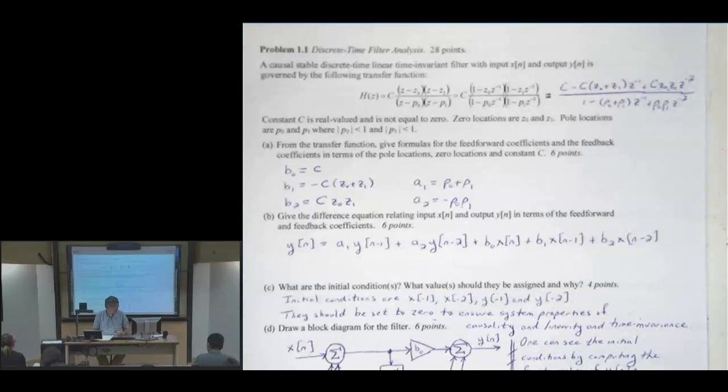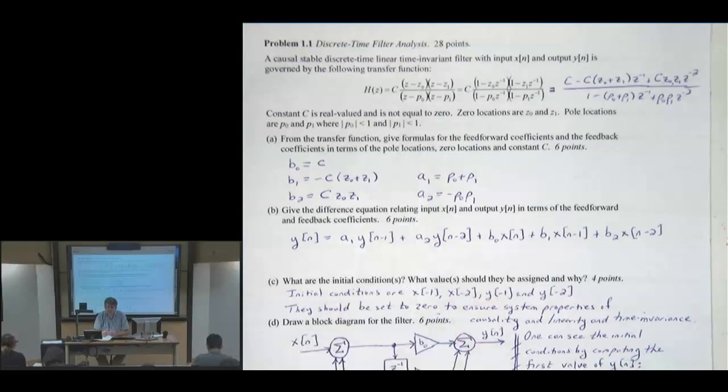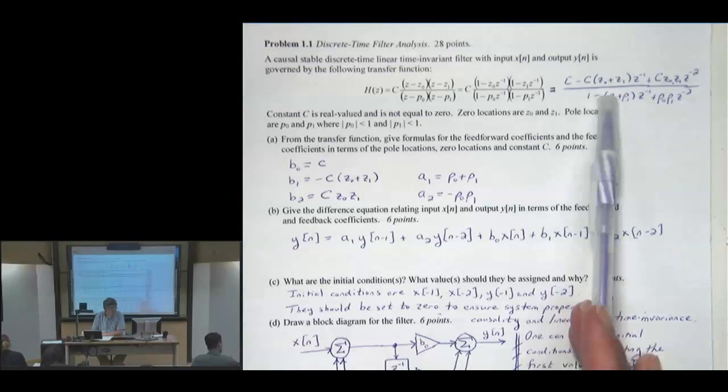So I went ahead and expanded the polynomial up here. So this is a biquad in pole-zero-gain form. We have a list of zeros, Z0, Z1, a list of poles, P0, P1, and a gain, capital C. At this point in the problem for part A, we don't really need the gain for anything in this problem. In the end, you can set it to 1 if you like. It doesn't change things in part E if you want. Right now I'm just asking you to work with the factored form and then give the unfactored form and then find the coefficients as a result.